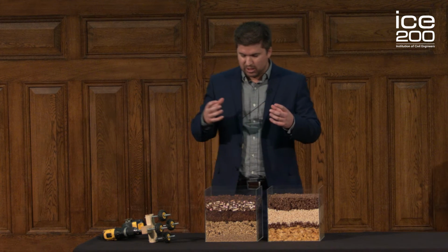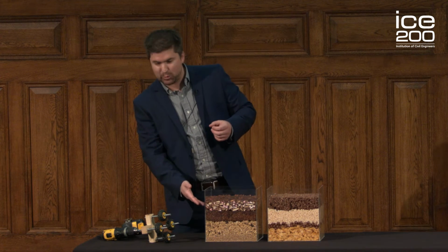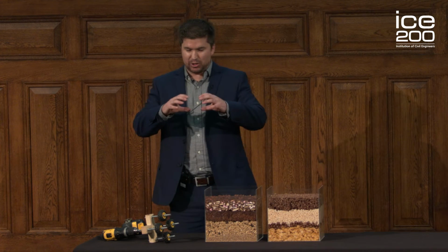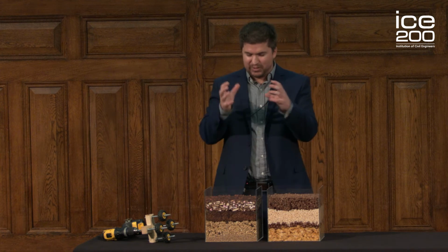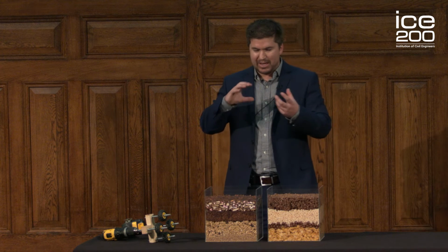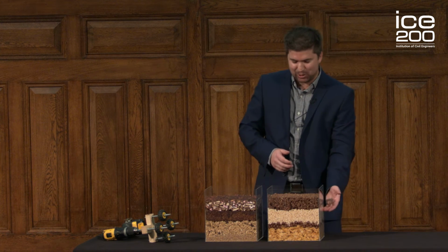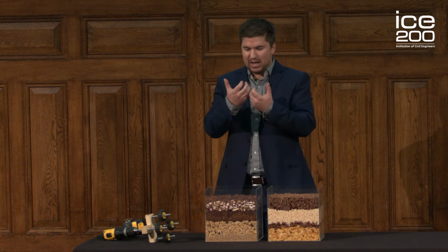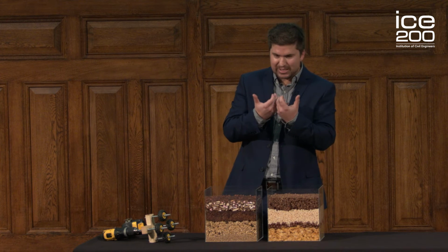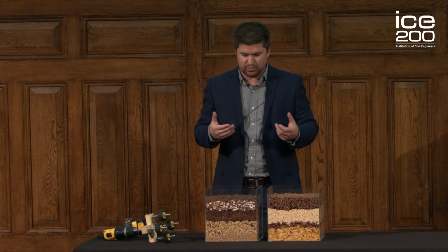Again, this is a granular material to provide more strength. So in the good pavement example, we've got a flapjack here. So all of the oats in there, it's lots of different shaped particles, if you like, which represent the aggregates, and they interlock well to form a strong layer. What you don't want is the Rice Krispies, which are all very rounded, and under the loading of the traffic, they gradually slip against each other, again settling and disturbing the pavement over the top.